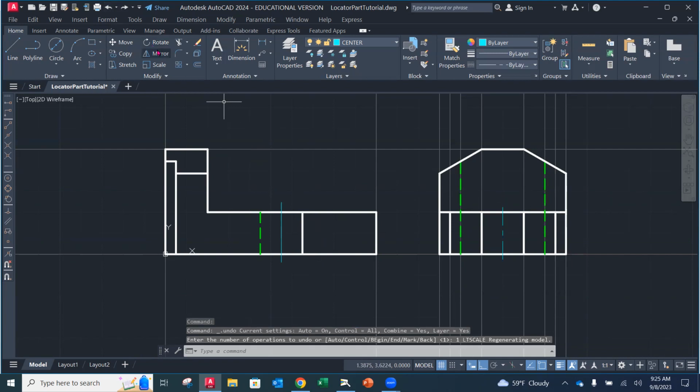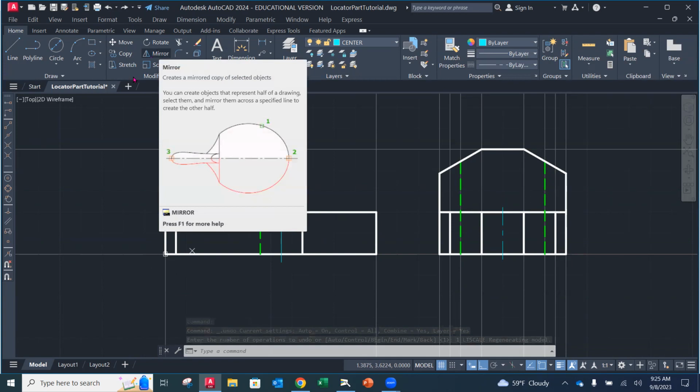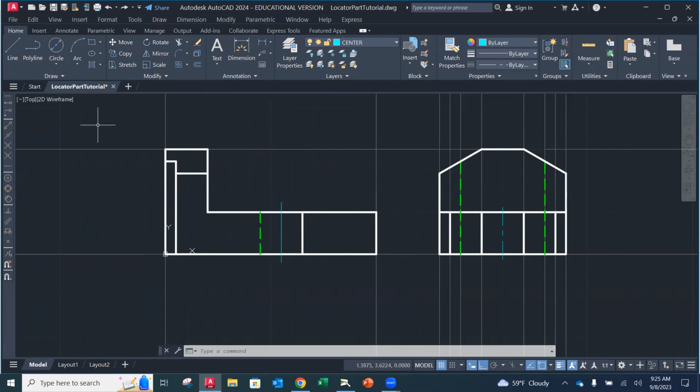So when you do LT scale, and sometimes you may want to because your whole drawing is wrong at the moment, then you do want to change them all. So that's the purpose of that. That LT scale command will put a blanket over everything and change that line type scale for everything, but it's not what we wanted. We only want to change the one.